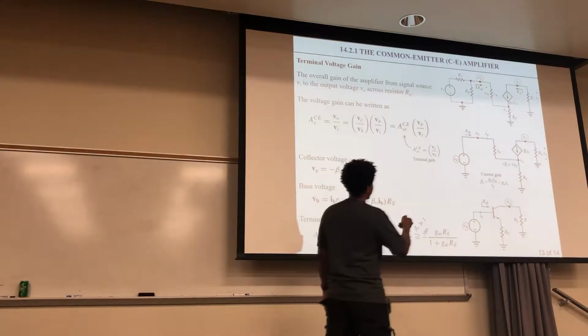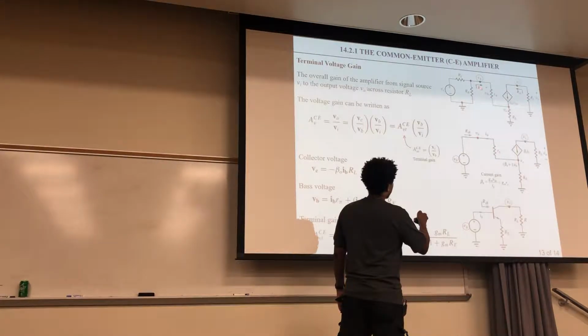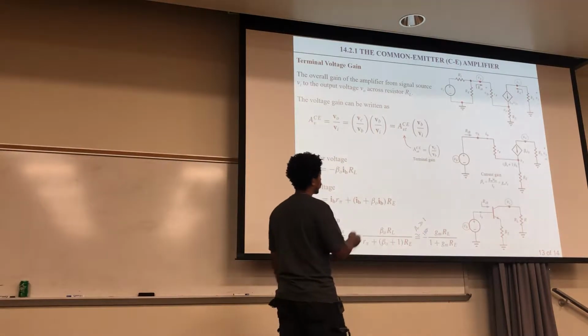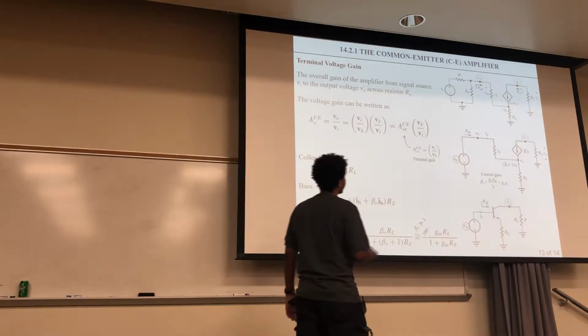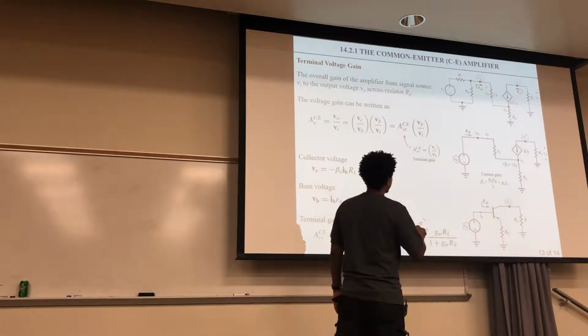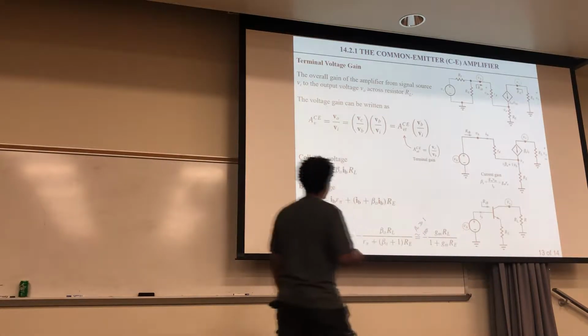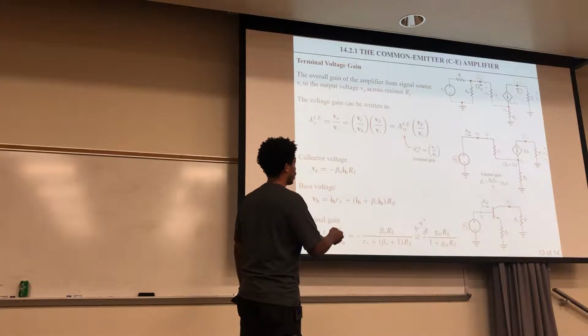Okay? And your RIB is your resistance looking at it from this point in this direction. So that's what this is. So you're no longer really considering these resistors right here because they're tied in there. So your current going through here is your IB, okay? And that's going downhill through that R pi.